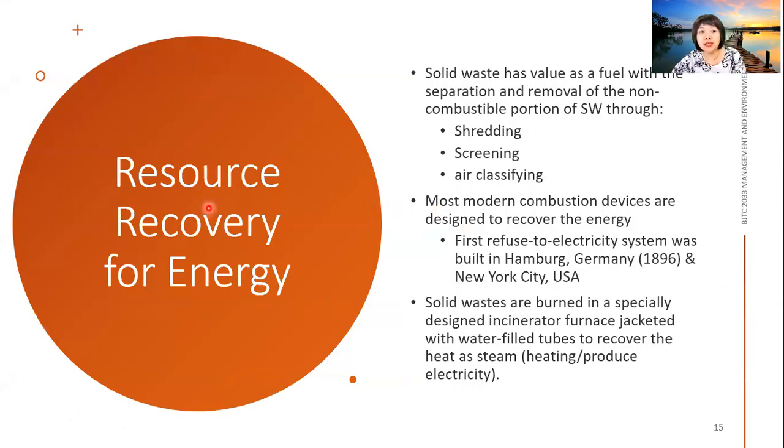Now, when we talk about resource recovery for energy, all the rubbish and solid waste that we have can actually be converted into energy by using some technologies. But how do we do it? Solid waste has value as a fuel, with the separation and removal of the non-combustible portions of the solid waste through shredding, screening, and air classifying. The most modern combustion devices are designed to recover the energy.